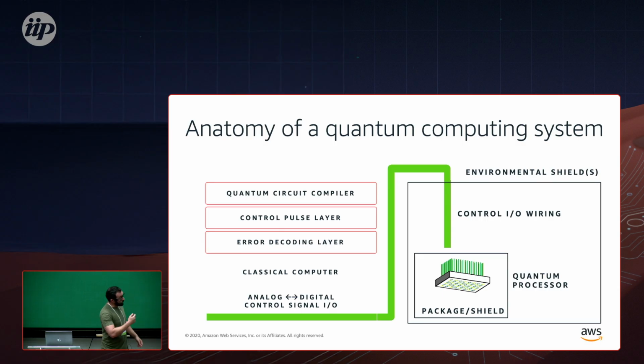So in the end, for the quantum computer, we always interface with a classical computer. We always program the quantum computer using a classical computer. So you want to send a quantum circuit, right? So there's a compiler that maps some higher level abstraction to the quantum circuit you want to send. We actually don't send instructions in terms of apply a CNOT gate, apply an X gate. We have to send pulses, right? In the case of superconducting qubits, as I mentioned, it's some microwave pulses, either some flux pulse or some actual microwave pulse, XY line. So there is a compiler, the map to control pulse layer.